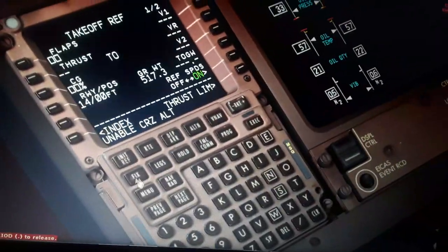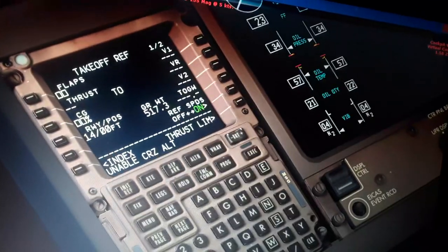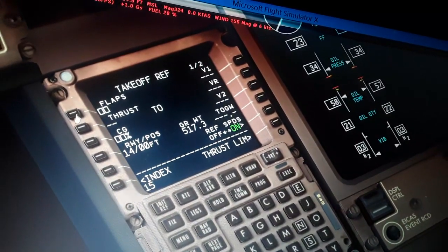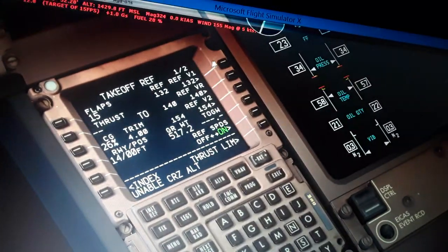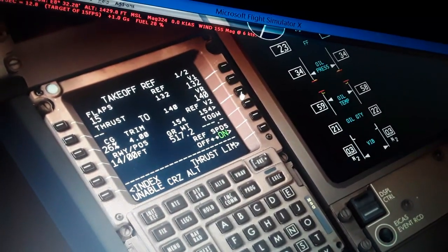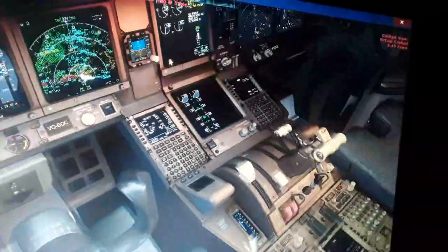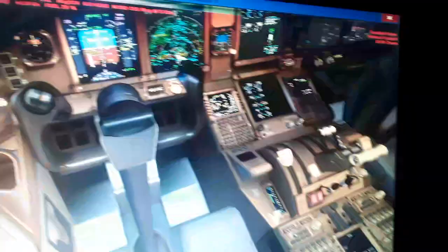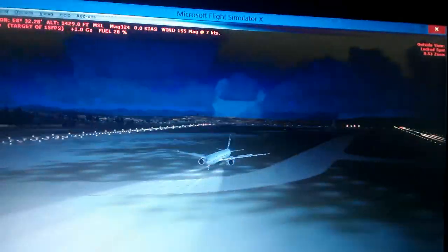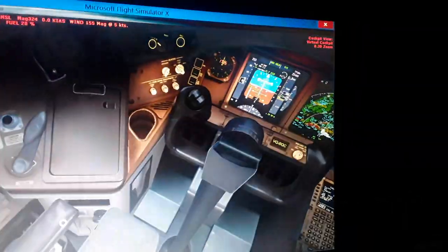So this is the complete route of the airplane. You only need one small step. The flaps we're going to use for takeoff using this runway, center of gravity over here, automatic with trim, and V1, V rotate, and V2. We have the takeoff speeds for this runway with this weight for takeoff. So everything is set. We can only taxi now into the runway. You can take off. We have like 15 minutes.